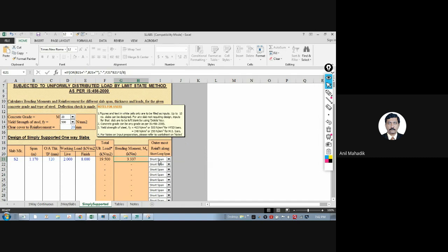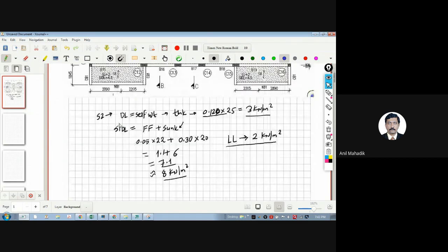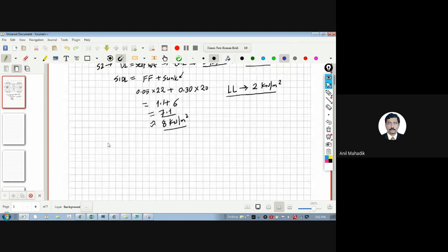I think last time we discussed this in slabs, one-way slab. As this is your direction of the slab, then your main steel will also be in that direction, this one. So this main steel will be outermost, and there will be distribution steel, which is horizontal, above the main steel. So if you see the section, last time also in the drawing session we have discussed this. If you see this section A, then how will it look like?